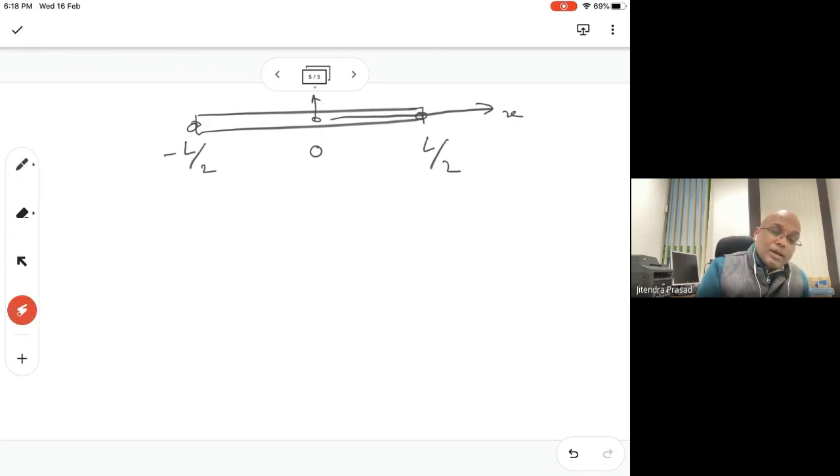What we are doing, we can just derive first. We are going to derive the equation given this system, because whether this system starts here or here doesn't matter. So we have to take care of it accordingly. And since B naught is constant, the body force is independent of this axis system anyway. We are not writing Bx as some value. This is B naught, Bx equal to B naught. Even if you change the axis, B naught remains B naught only. But in any case, for finding the stiffness matrix, you can change the axis system accordingly.